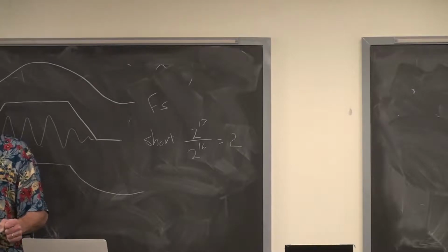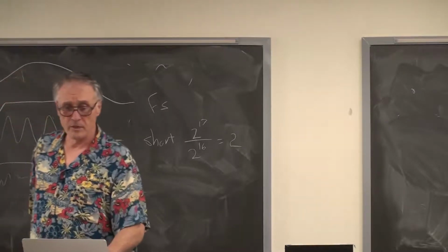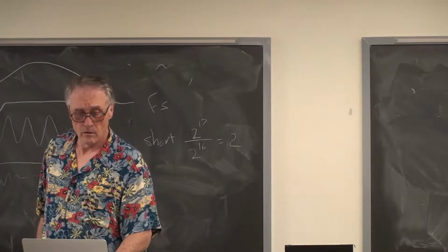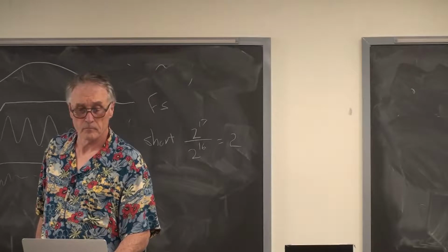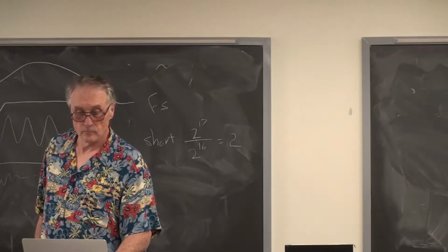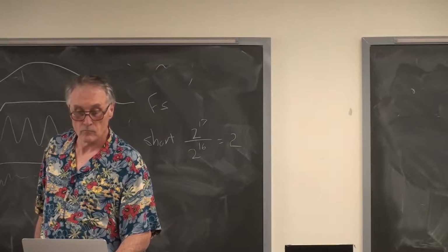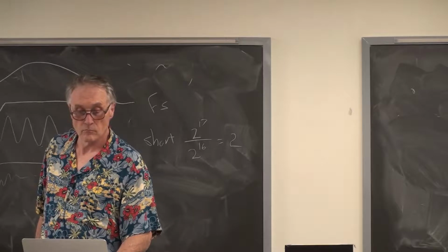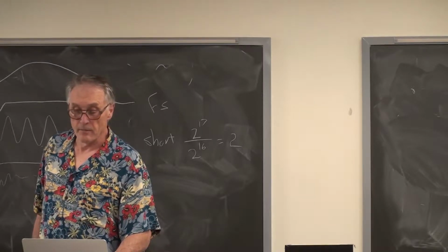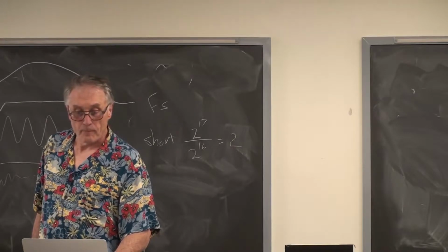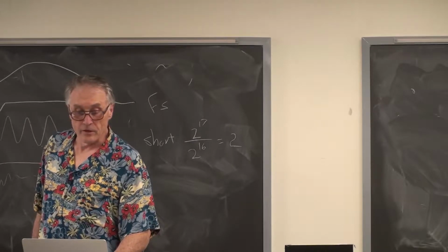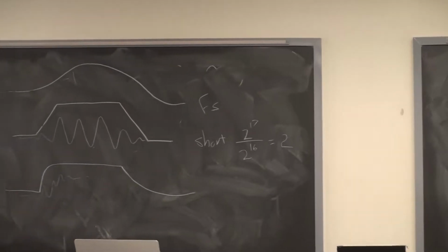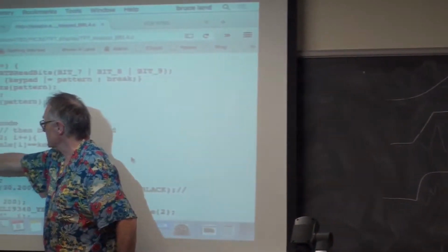And remember, there's an error in my code. Where was that? If we go to the keypad test code, the thread which scans the keypad every 30 milliseconds returns an incorrect value if you press 2 buttons because I did not initialize the index to -1.